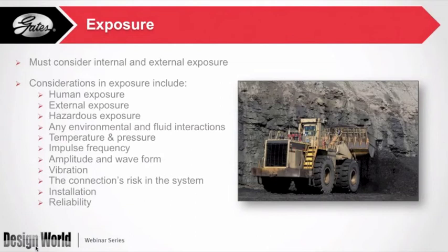So you want to make sure that you pick the appropriate hose that's going to meet as much of that need as possible. Hazardous exposure: there are all types of chemicals used in compounding the cover of the hoses or the O-rings in the couplings that have to handle all kinds of hazardous exposure, everything from sodium hydroxide to chlorine. So if it's a hazardous situation, you want to make sure you pick the appropriate hose and couplings so that you're not going to have a spill and expose someone to a problem or a spill.